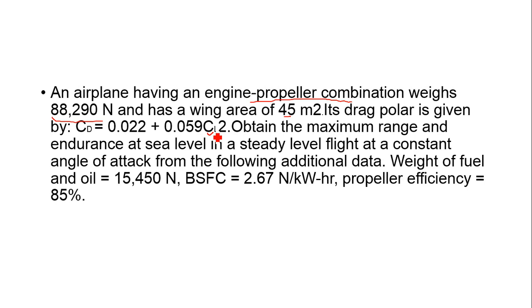Because of this equation, CD equals CDO plus K CL square, that is what is given. So CD equals 0.022 plus 0.059 CL square. We need to obtain the maximum range and endurance at sea level, in a steady level flight at a constant angle of attack.